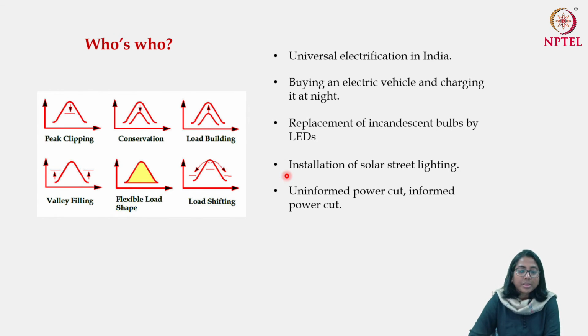If this happens during your peak demand period, then you may suggest that this is an activity which is leading to peak clipping, because your energy demand in the peak period has been forced to come down. However, I would like to recommend that it's better not to call it peak clipping, because this kind of event is not at all a sort of load management.